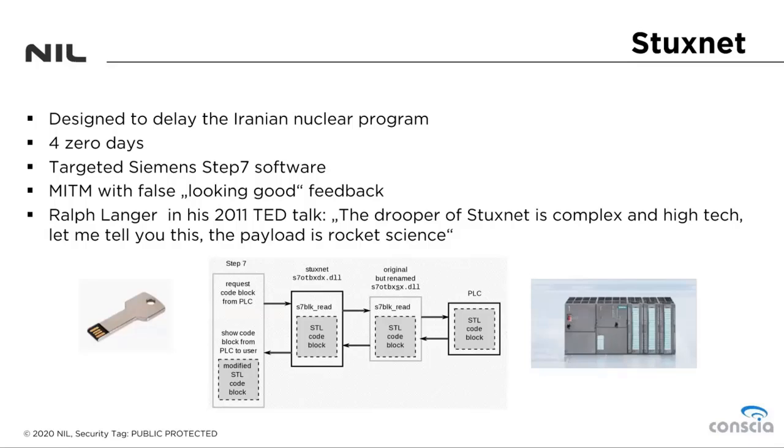But once Stuxnet is on the system, it infects project files of the Siemens WinCC SCADA control software and replaces a key communication library of WinCC. When the malicious code is deployed on the PLC, an attack routine starts to execute. There were actually 2 attack routines discovered, but only one was used. In the attack routine, Stuxnet tries to overspeed the rotors of the centrifuges, and it was very effective in doing so because it destroyed almost 20% of the centrifuges.